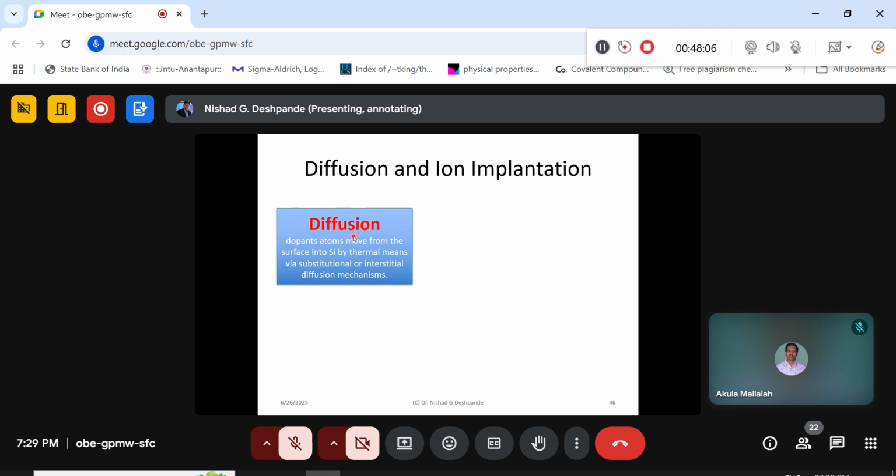Okay, so that is one of the processes where you have such a diffusion. Using this process, one can again input some dopants into the silicon substrate. Please don't get confused between two different processes I mentioned here. I just mentioned one process where you are talking about silicon oxidation. In that process, the silicon surface is there, you have oxygen which was inputted, and that oxygen moves towards the silicon surface.